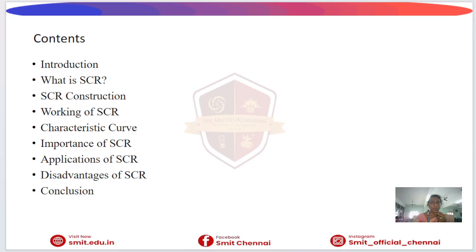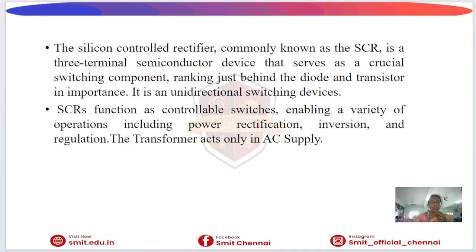So first, the introduction. What is silicon control rectifier? SCR stands for silicon control rectifier. It is a semiconductor switching device belonging to the thyristor family, and the SCR is called a control rectifier because the diode conducts automatically when it is forward biased, and SCR conducts only when it receives the triggering signal at the gate terminal, so that we can control when current starts flowing.